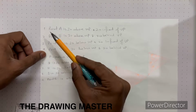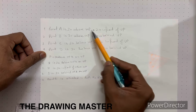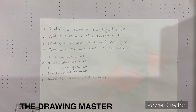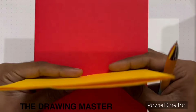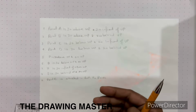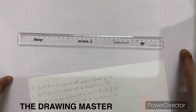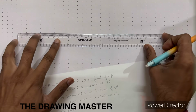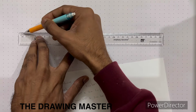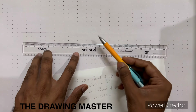Okay. So let's draw the projection of the following points. Point A is 30 above HP and 20 in front of VP. In which quadrant is it? Above HP and in front of VP. So this is first quadrant. Sometimes it is asked in which quadrant it is. Let's prepare its drawing. For the drawing, 3 steps are there. The very first step is to draw the reference line. I will draw one common reference line here. The reference line should always be a thin, continuous line.